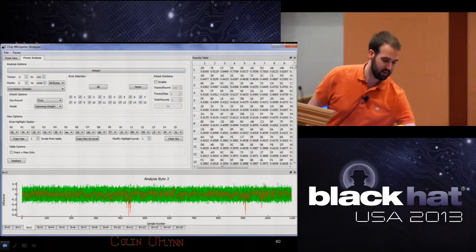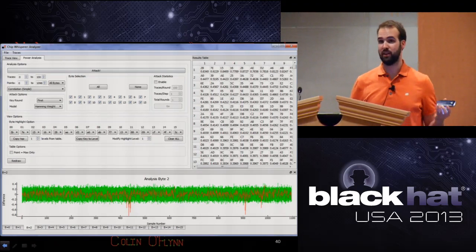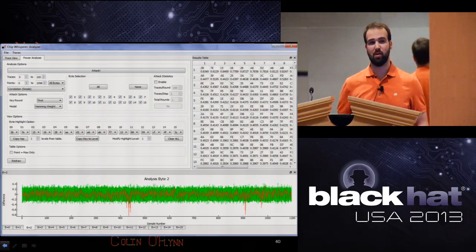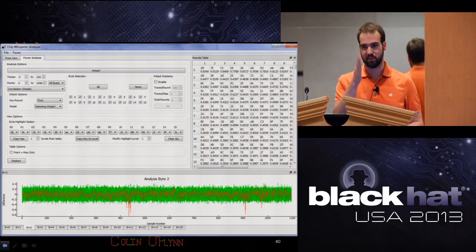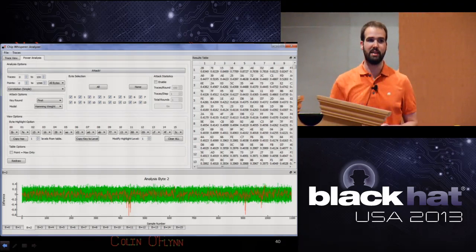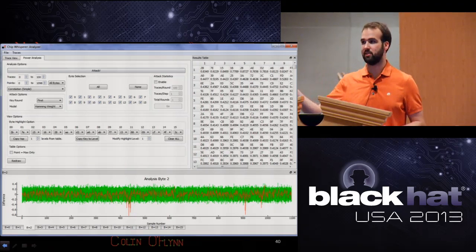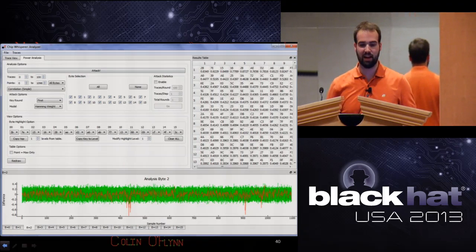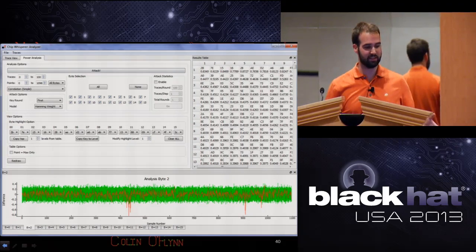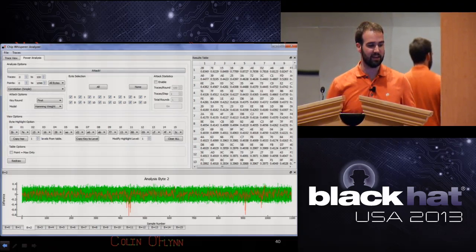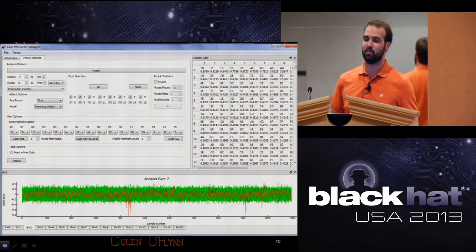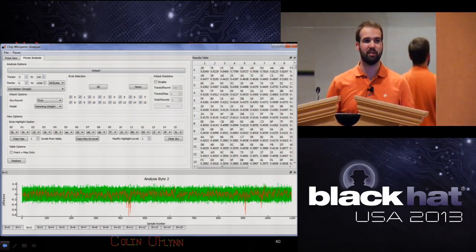If you're doing a cell phone that maybe is running at hundreds of megahertz and it's doing the AES in software, you can get away with a pretty slow capture because it's not doing something every clock cycle. So you don't necessarily need to measure every single clock cycle on the data. You can average over a bunch. It's really highly dependent on the hardware. But the idea of the synchronized capture also is that worst case you would have to buy a faster ADC, which still isn't super expensive. You can get a gigahertz sample ADC for a few hundred dollars.